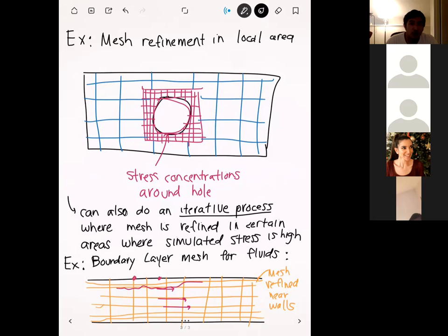So you really want to apply a refined mesh in the areas you're interested in, and for the other parts that you don't care about, you can either suppress them or use a coarse mesh. The quality of your mesh really determines the quality of your simulation, so it's something to really pay attention to.